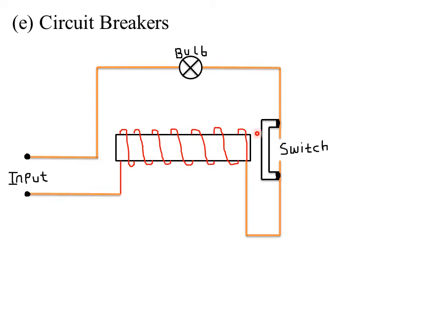Then we have said that the advantage of a circuit breaker over a fuse is that once the problem that was causing the excess current has been corrected, you can simply reset the circuit breaker by taking this particular material that is completing our circuit. You just take it back mechanically, unlike for a fuse which blows off when excessive current flows through. So that means for the case of a fuse, you have to buy a new one. But for a circuit breaker, you just reattach this part back to the switch.